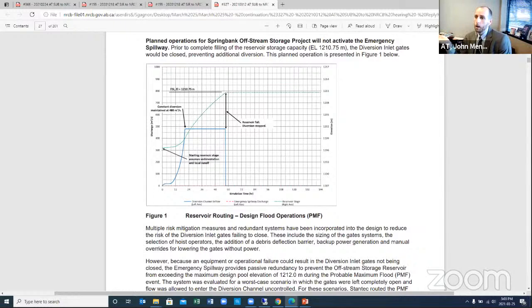Sure. And again, our design mitigates the majority of these scenarios, but often with embankment dams, there may be a seep identified on the downstream side of the dam that is indicating the potential for water flowing through the foundation or embankment. In those scenarios, you would mitigate by adding filters and other components to control the flows coming through the embankment and to arrest any transmission of material or particles from the embankment. That would be one.